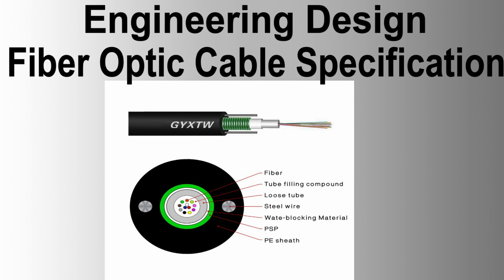Optical point discontinuities at 1550 nanometers, 0.05 dB. Chromatic dispersion at 1550 nanometers, 2.6 to 6 ps per nanometer kilometer. PMD coefficient, 0.2 ps per root kilometer. Environmental performance of cable, operating temperature, as per section 4.2. Allowable change in attenuation at temperature extremes, 0.58 dB per kilometer. Installation temperature, as per section 4.2, storage temperature, minus 10 to plus 85 degrees Celsius.